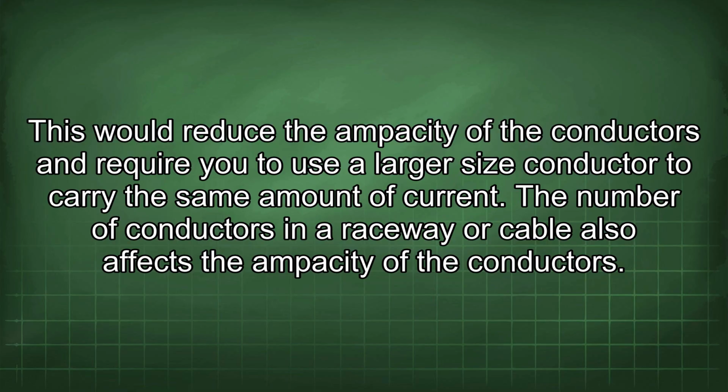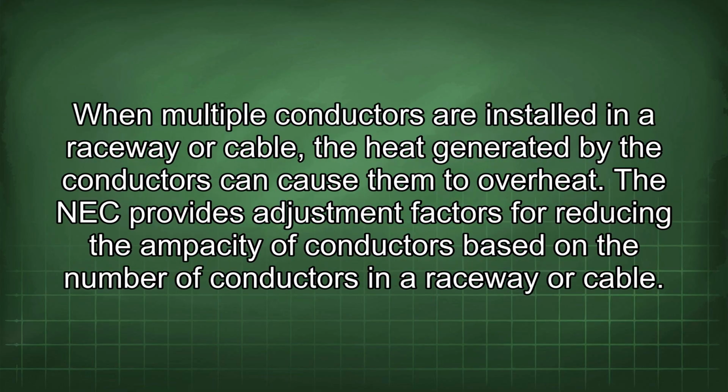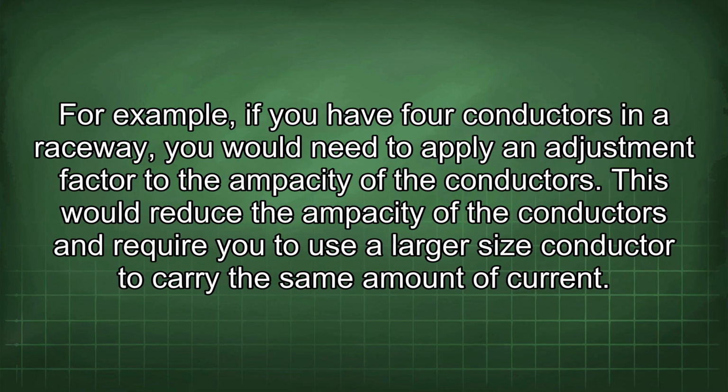same amount of current. The number of conductors in a raceway or cable also affects the ampacity of the conductors. When multiple conductors are installed in a raceway or cable, heat generated by the conductors can cause them to overheat. The NEC provides adjustment factors for reducing the ampacity of conductors based on the number of conductors in a raceway or cable. For example, if you have 4 conductors in a raceway, you would need to apply an adjustment factor to the ampacity of the conductors. This would reduce the ampacity of the conductors and require you to use a larger size conductor to carry the